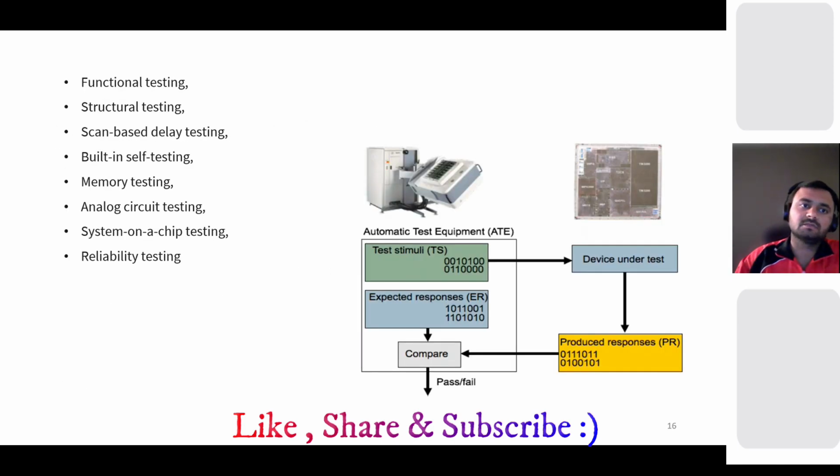And there are many more. We do functional testing, structural testing, scan-based delay testing, built-in self test, memory testing, analog circuit testing, system on chip testing, and reliability testing, and basically those things happen on the ATE, automatic test equipment. Once you have the silicon in your hand, you deliver it to the test team, the ATE team, and you also deliver the ATPG patterns which you generated on the PNR netlist.